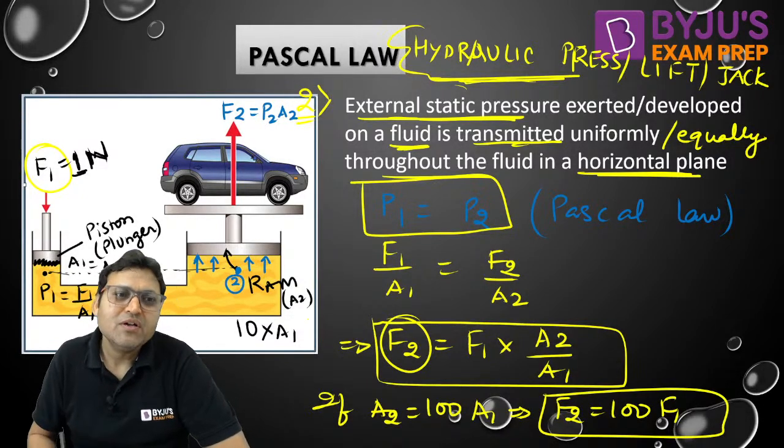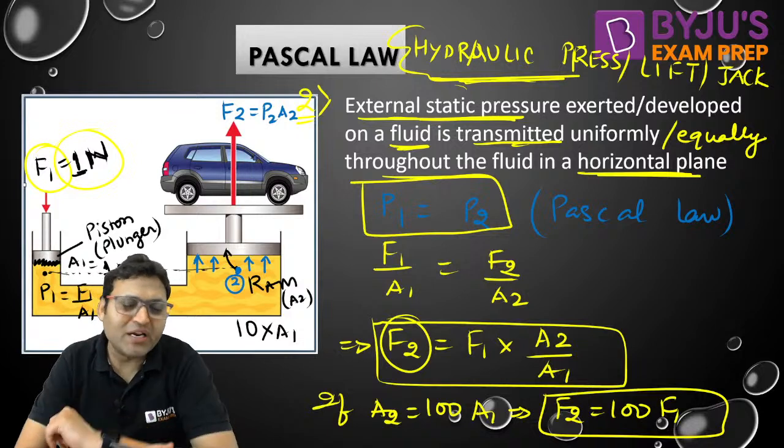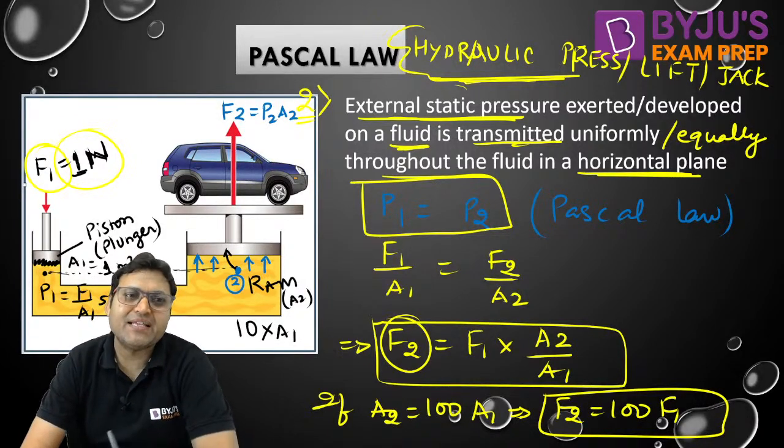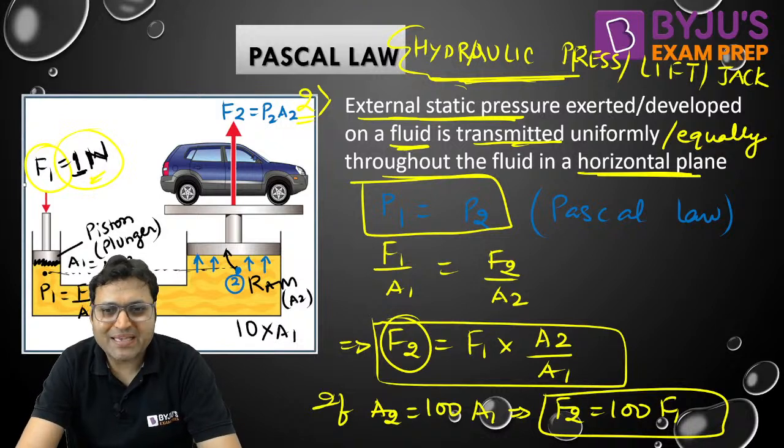That is how, by applying 1 Newton of force, we can get 100 Newtons of force at the ram, and a 100 Newton load can be easily lifted by just applying 1 Newton of force. That is Pascal's law. I hope this is clear.